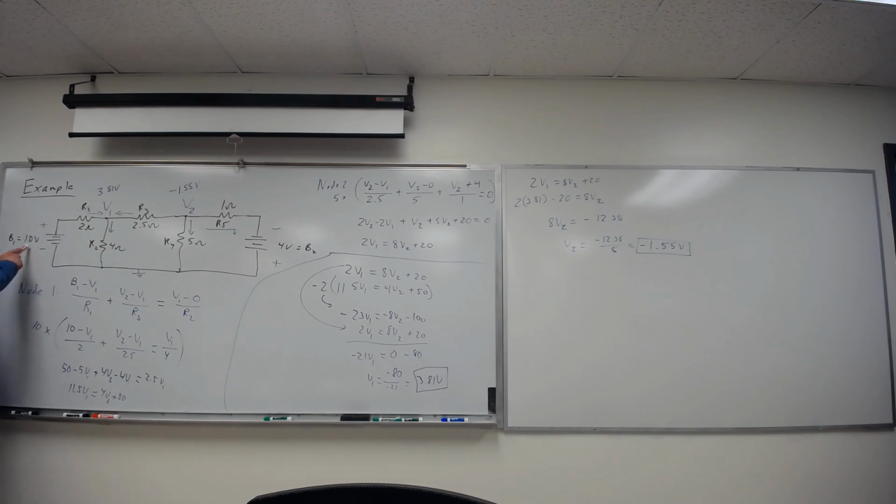Well, I know that 10 volts, if I go around here, I still have my loop concept. If I put 10 volts in, this voltage plus this has to equal 10 volts. So what I was just saying, Joe, is this voltage plus this voltage have to equal 10 volts. So if that's 3.81 volts, that doesn't mean it's necessarily right, but it's less than 10, and it seems like a reasonable number when you have these two. How do I find out? Oh, well, let's do this.